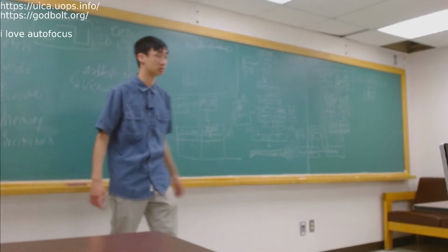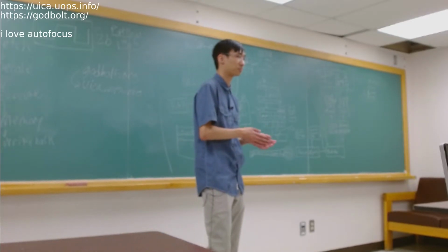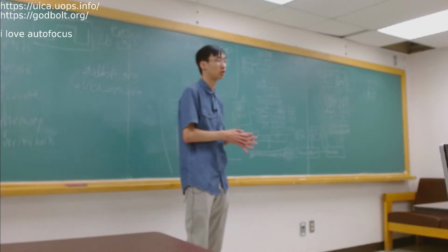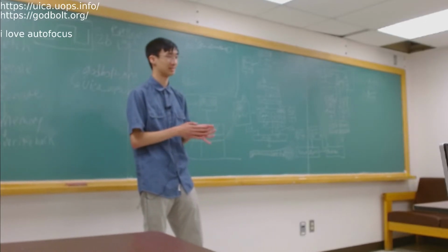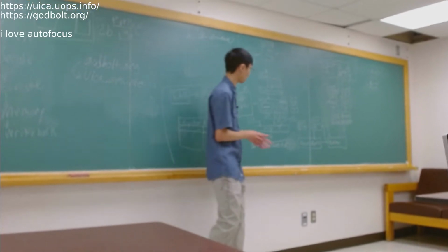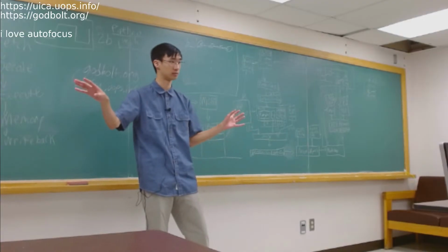The overview, yeah. For branch misprediction, right? Yes. It flushes any instructions, if it mispredicts. In theory, it should only flush instructions related to the mispredict, but it could also just flush the entire CPU. Oh, okay. So whenever it flushes instructions, how does it know how many instructions to flush there? The branch order buffer. The branch order buffer will give you a snapshot of what happened, and it will be able to use that to figure out which architectural registers are not useful and which instructions are not useful and remove them.